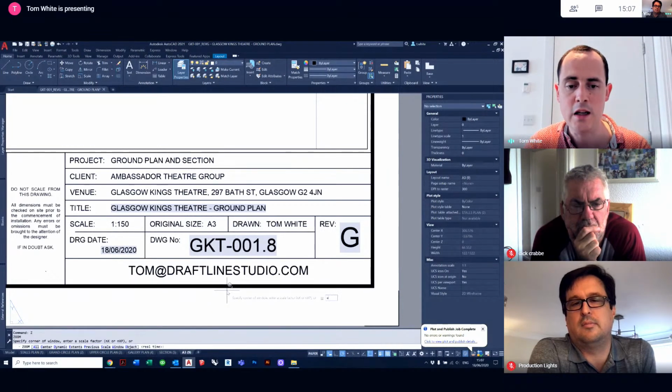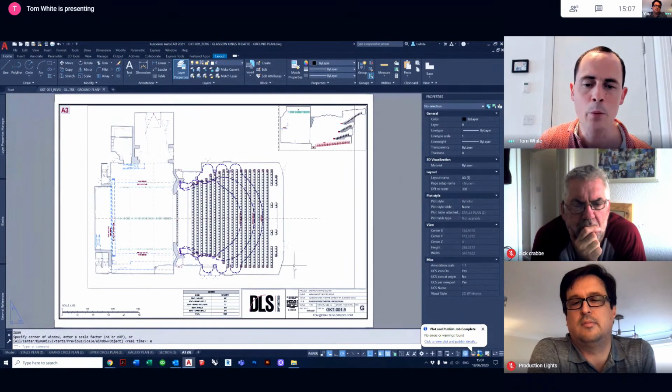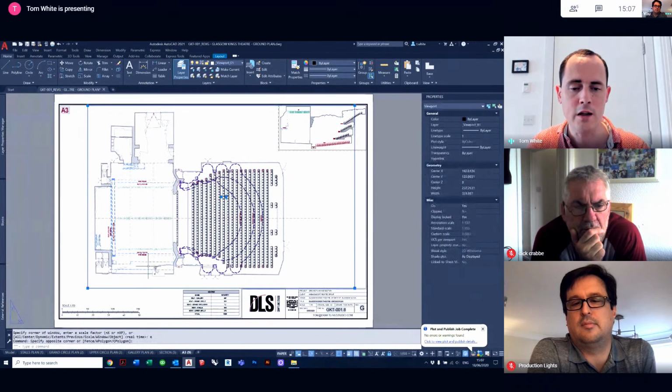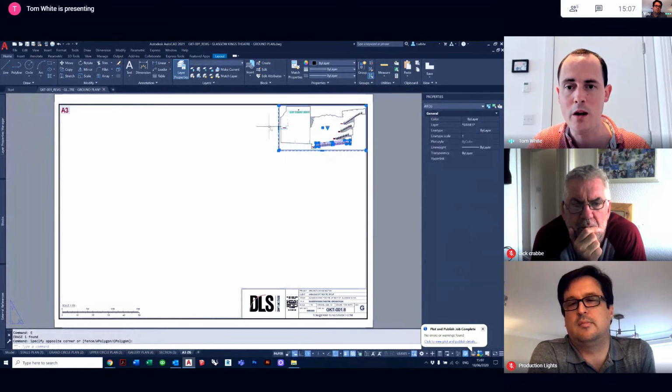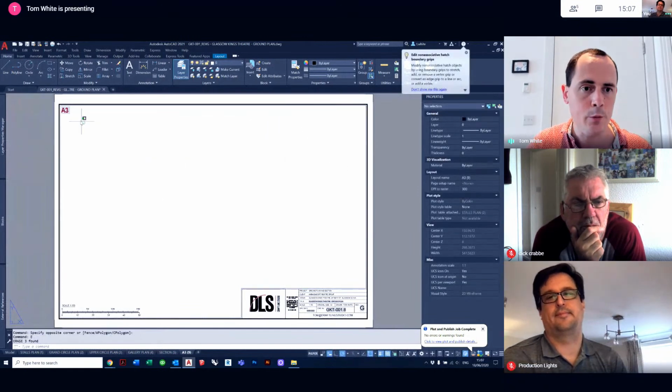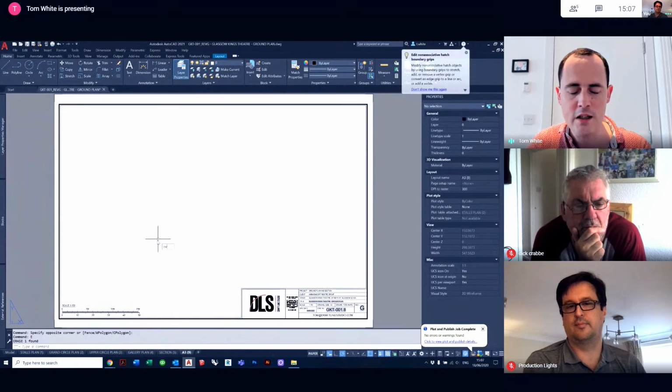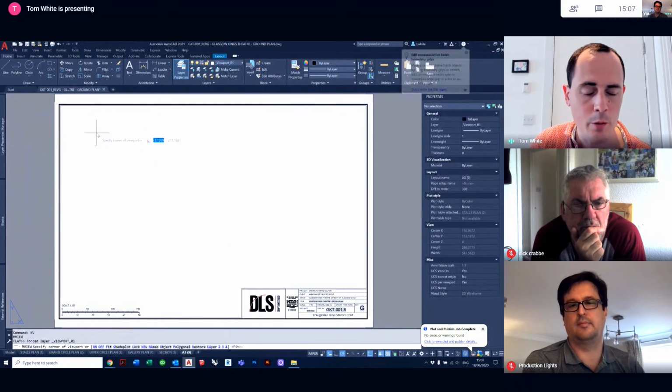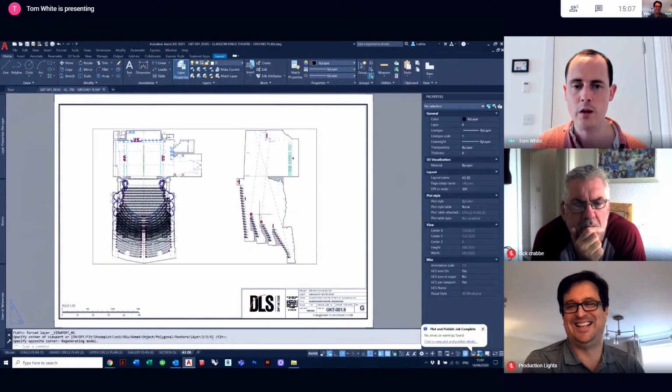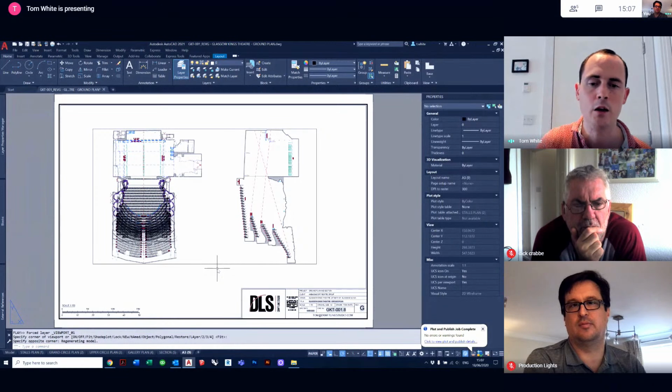So Z enter, E enter to zoom extents. And what I'm going to do now is erase everything in this piece of paper. And I am also going to erase this. And what I need to tell Dick, I apologize, is this room. So what I have here is I've done new viewport to produce a viewport into our model space. That's a rectangle. You can do it as a polyline, you can do it as a circle, but in this circumstance, I've just done a rectangle.